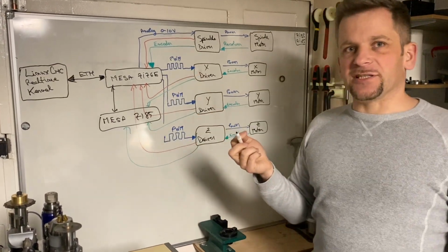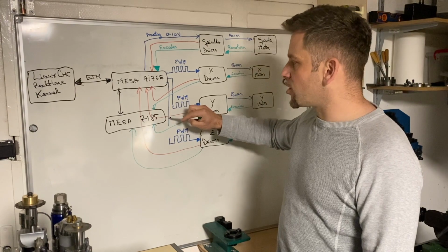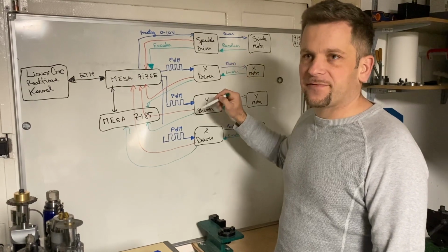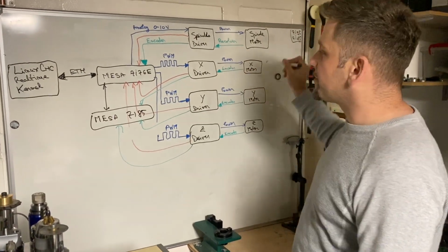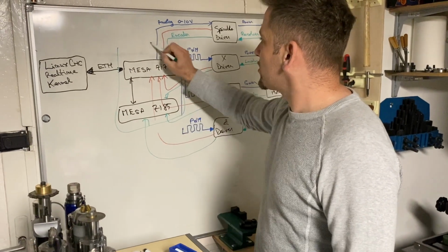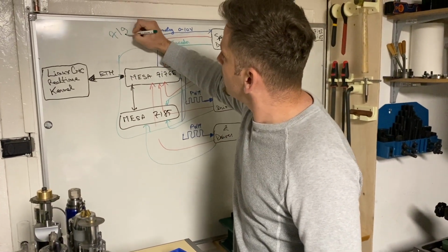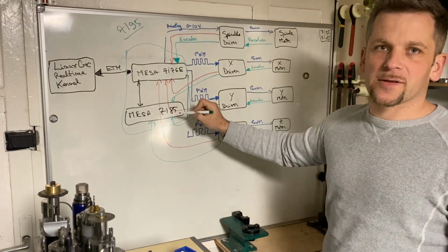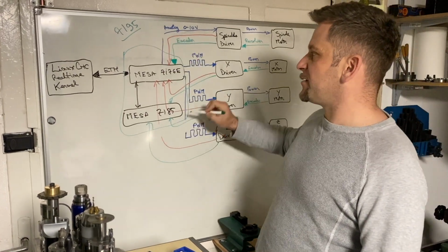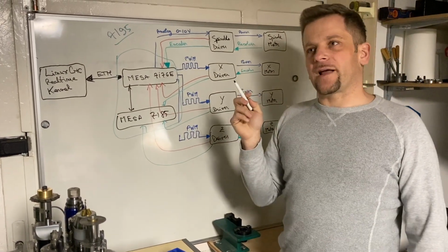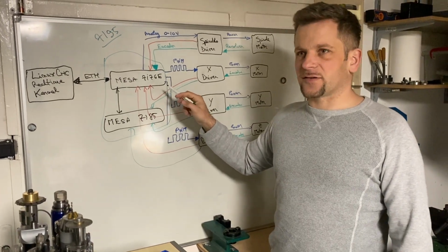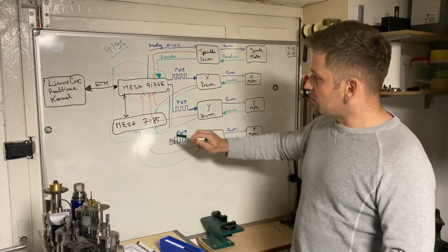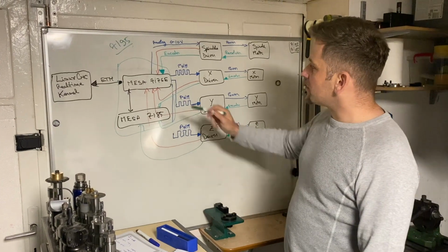If you're building a new machine and you need encoder inputs, and I would recommend encoder inputs if your drives have them, and mine do, I would recommend a 7i95. A 7i95 board is basically a Mesa 7i76 that has encoder inputs. So that's a board that has both of them. I don't know exactly if, when I ordered this about 3 years ago or so, this was already on the market, but I had no idea about it. So this is already ordered, this board. So I'm going to link them together.